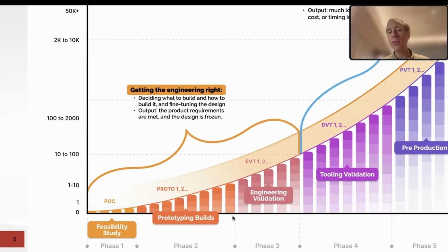And of course, prototyping iterations, right? So you're going to get prototypes in different design iterations. Now, every design iteration comes with its own design files, so you would expect to get the native files here. And you would also expect to have test reports. So it means that a test plan and maybe a checklist need to be developed, and then every prototype needs to be reviewed against that checklist and that test plan.